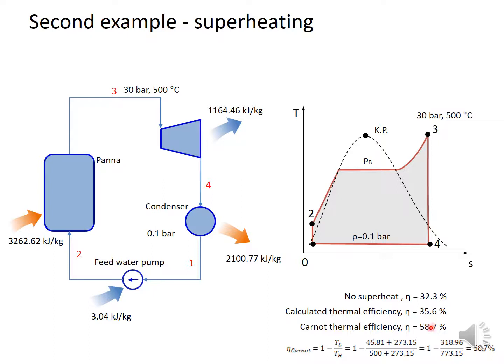That basically means that I have used this line here as the highest temperature for which the Carnot engine would be able to work, and you see here that that is not the case for the Rankine cycle. And again, although we increased this quite a lot, the turbine work and the pump work are still the same. We do, however, have to push a lot more heat into the system as well.